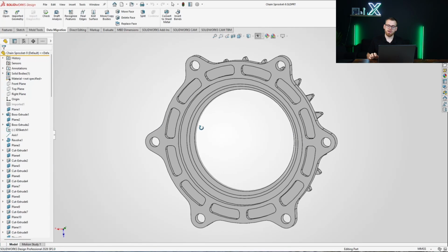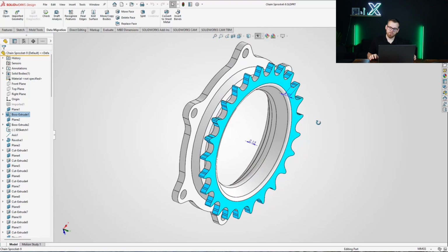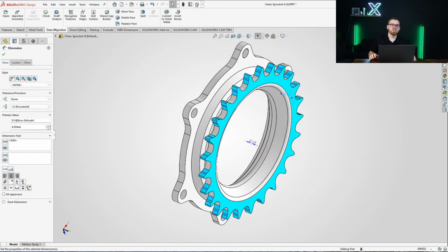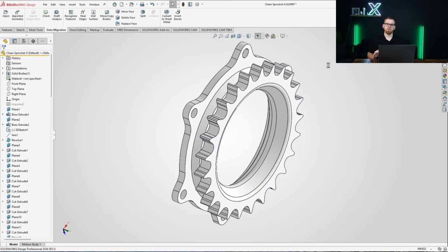We will then select Generate Preview, in which you'll see all of the features are filled up in the Feature Manager tree on the left-hand pane. And you can edit each of these and all of the associated dimensions, just as you would any other geometry within SOLIDWORKS. So it basically turns an imported body into a native SOLIDWORKS file. This tool can also be launched from the AI Labs menu. However, in this case, we did insert because we didn't need to change anything through prompts.